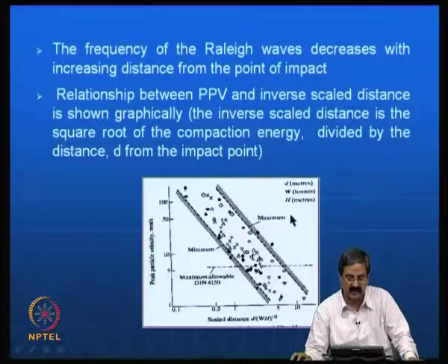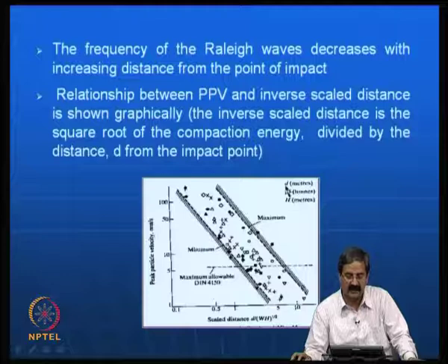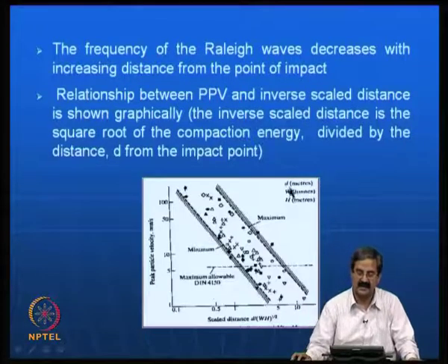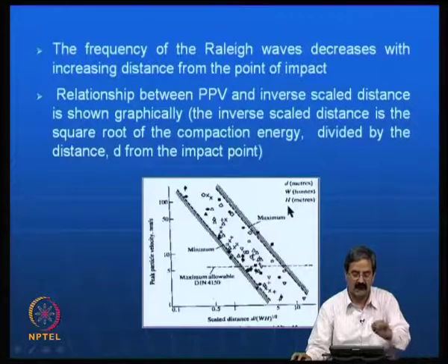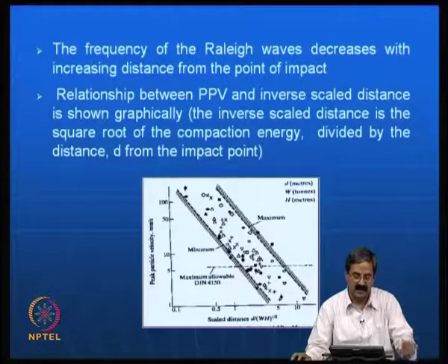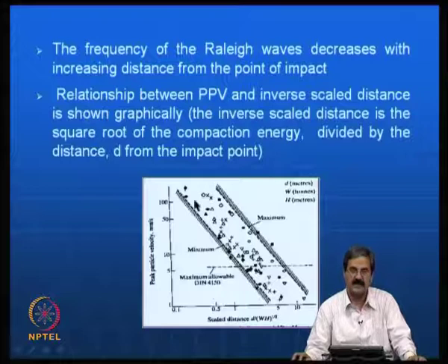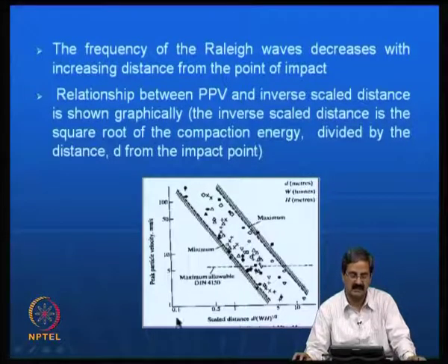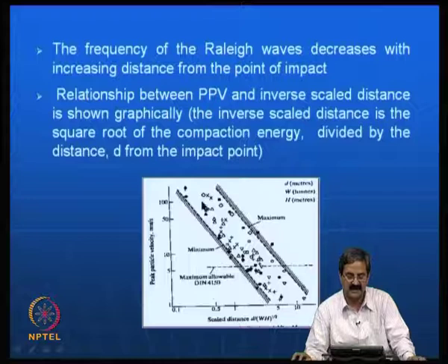different parameters are given here: distance in meters, weight in tons, and height. All the parameters are plotted, and then the maximum allowable range as per the German standard, DIN 4150. If the material falls in this range, it is acceptable, that is what they say.